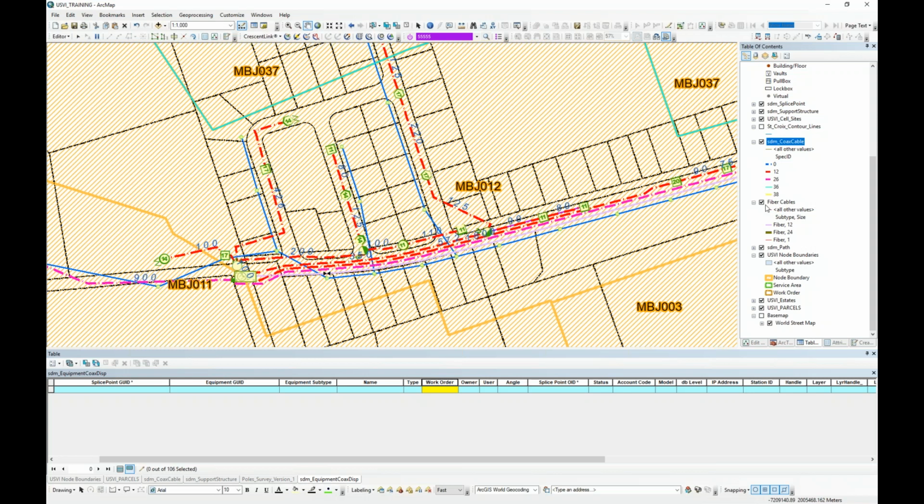So generally, we'll categorize it as trunk, distribution, and drop, and then within those, they're separate entities, and you have to look in the table to see what it is. So you have a 4-fiber drop, 2-fiber drop, 12-fiber. Distribution cable is 12 or 24, sometimes 48, all the way up to 144, and then you have trunk beyond that. So if need be, we can break it down even further, but we try not to. Some of our distribution cables are 288. Really? Yeah. We just label it. Depends on what you're using it for. You label it. We just label it so we know what it is.